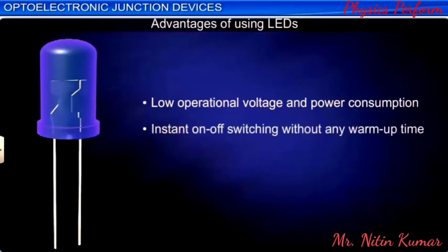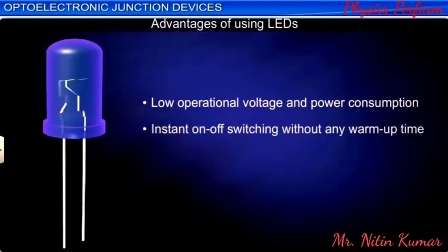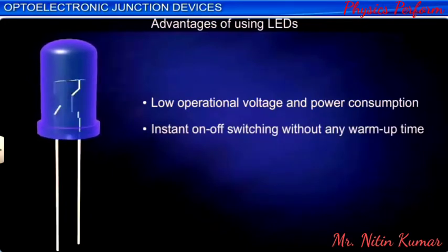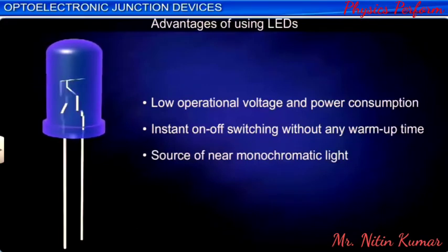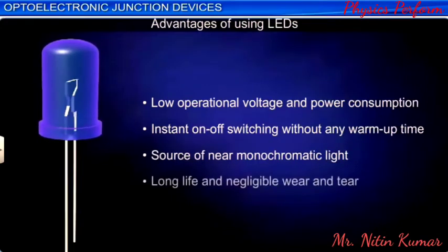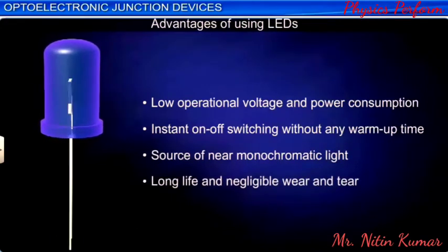LEDs have low reverse bias breakdown voltages. Thus, care must be taken that they do not get connected in reverse bias across a high voltage source.